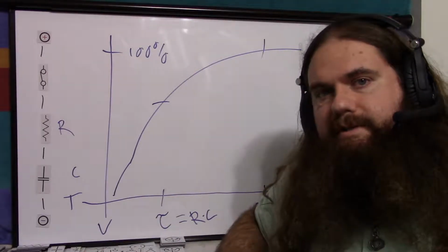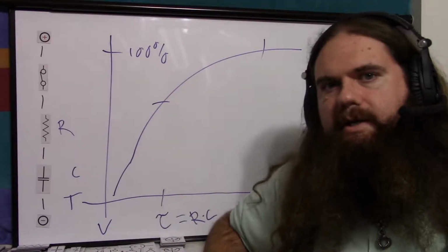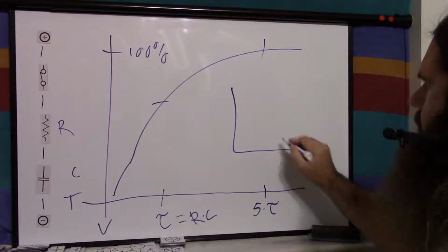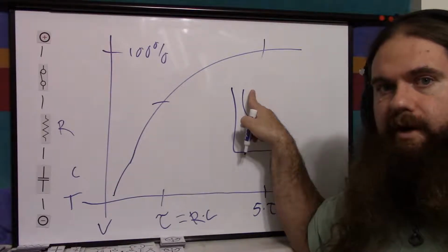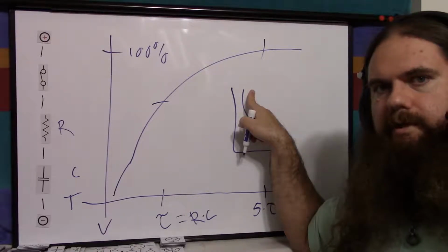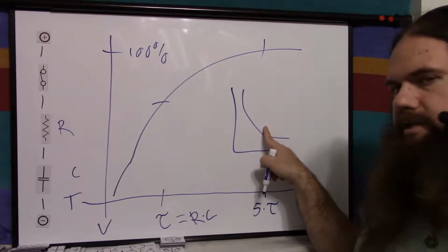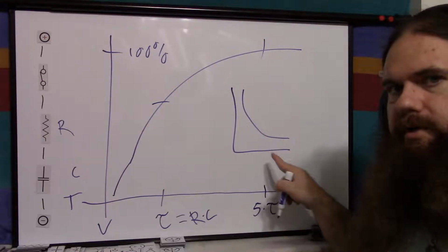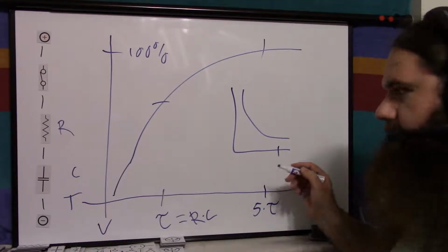And the opposite, that's the discharge time as well. If you have one that's fully charged, 5 tau will get it down effectively to 0. And unsurprisingly, that graph looks similar. It will decrease rapidly because, let's say, this is charged to 5 volts and you are putting 0 volts in the circuit with it. That's how you discharge. You have a lower voltage. So it decreases rapidly, but now let's say it's 2 volts and then you've got 0 volts. So there's less of a push because the voltage is pushing across the resistor. And it's the same thing. It goes to about 0 at 5 tau.